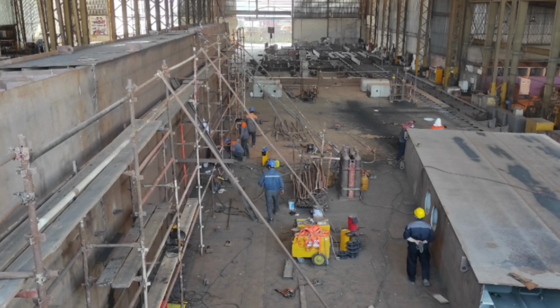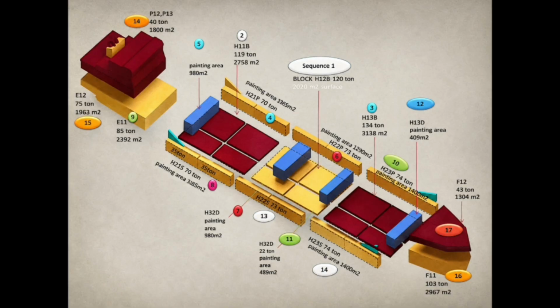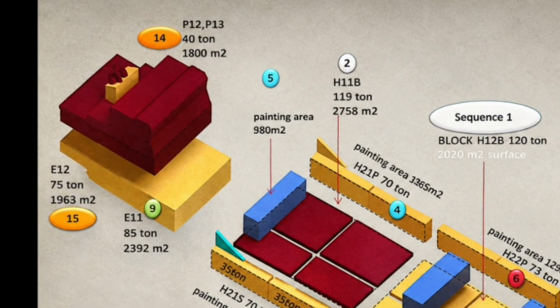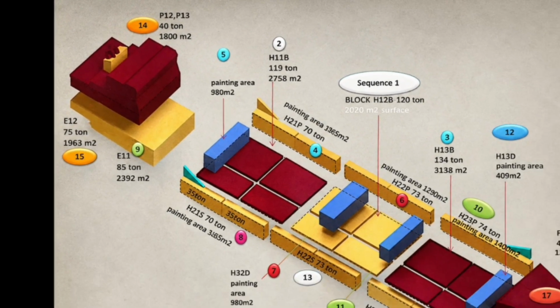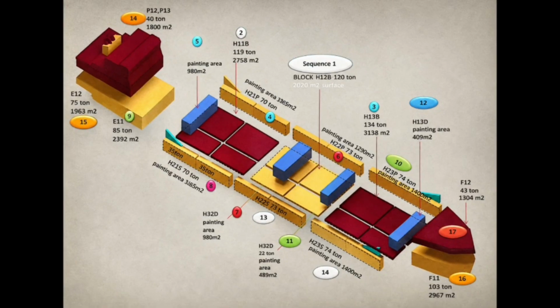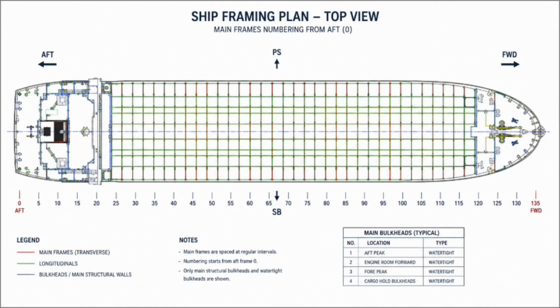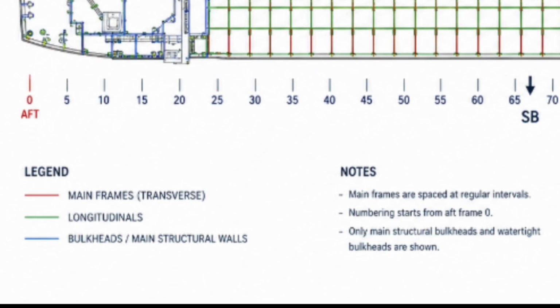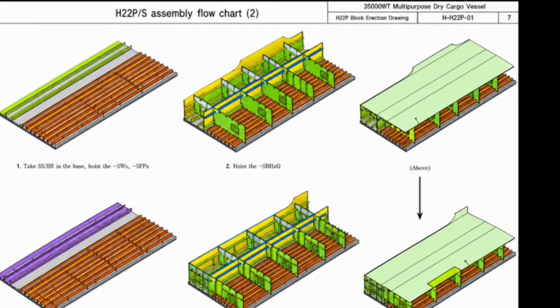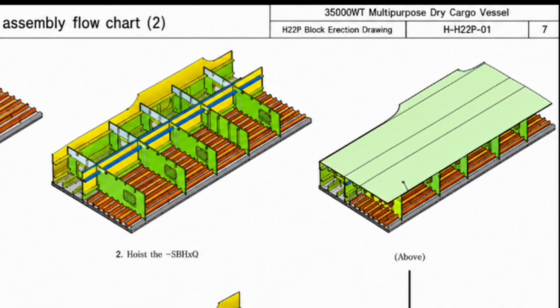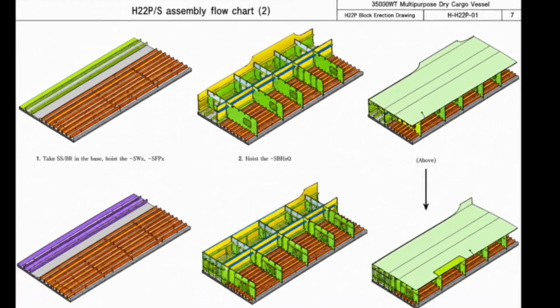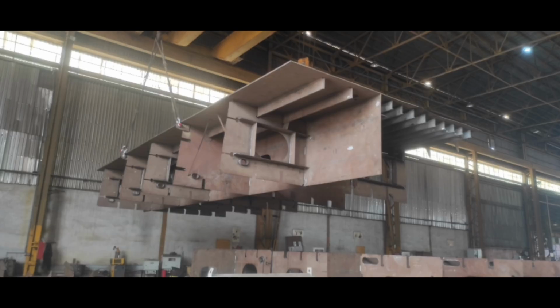During the ship design and construction process, we are not working with a completed vessel. Everything begins with a precise reference system. The ship's hull is divided into a series of frames, each identified by a frame number on the engineering drawings. The total number of frames depends on the length of the ship and the frame spacing, and these frame numbers serve as the primary reference for locating every structural component.